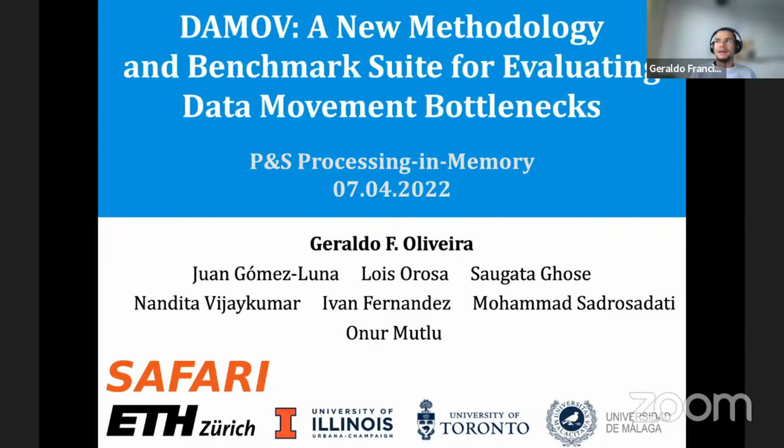The simulator is targeting the x86 ISA, but there are tricks you can employ to mimic the same type of ISA that these HBM PIM architectures are going to be executing, because in the end, it's just memory activations and memory precharges that are translated into issues to the PIM accelerator itself, which is already heavily supported by the simulator.